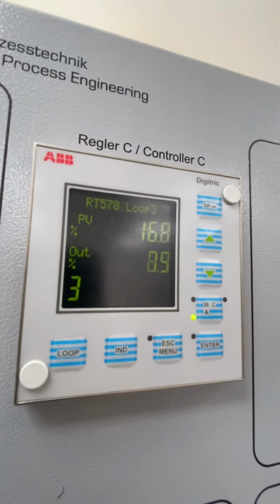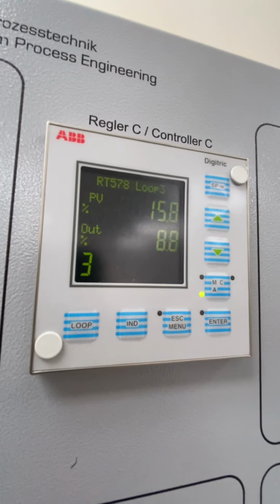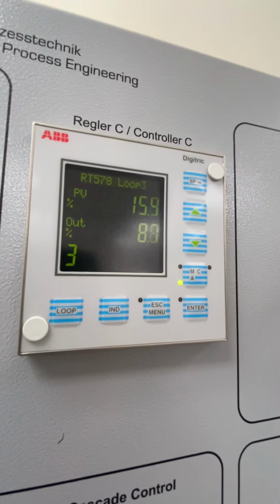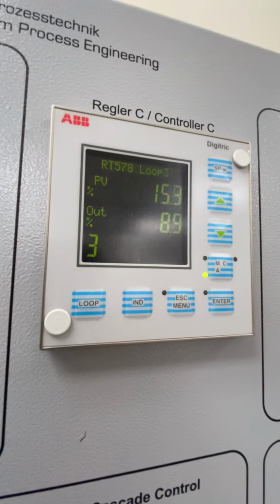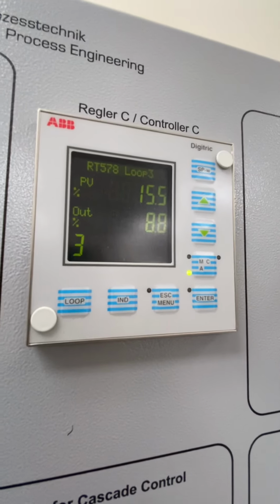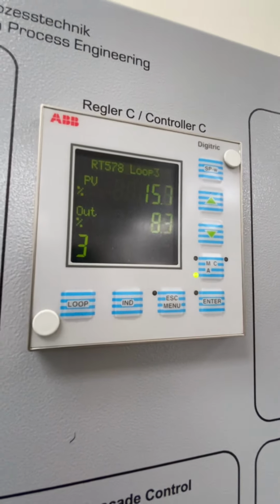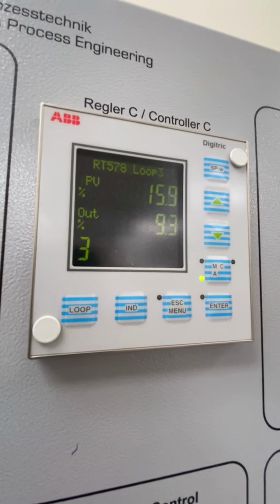So you see that there is a drop in the process value right now, okay? And the system is taking the necessary action to bring back the process value to the previous point, which is 20%. And eventually it will do that, guys. But what you are going to notice is that now we have a new output signal that is higher than the previous one.